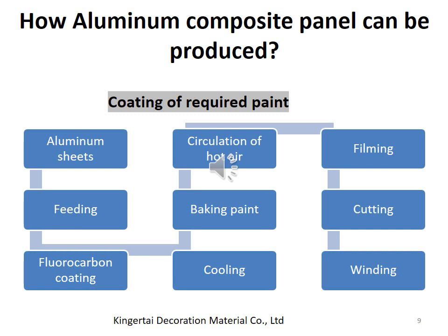Fluorocarbon coatings are usually applied to the aluminum coil by roll coating and then baked at elevated temperature to dry them. The equipment is continuously produced, first primed, then top coated, and finally coated with a surface varnish.